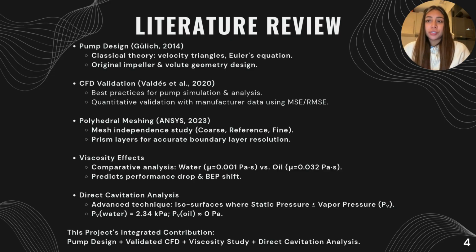In the literature, several key aspects guided our study. First, pump design theory based on classical turbomachinery concepts such as velocity triangles and Euler's equation was applied to define the impeller and volute geometry. Second, previous works like Valdez et al. provide best practices for CFD validation, including comparison with manufacturer data using error metrics.